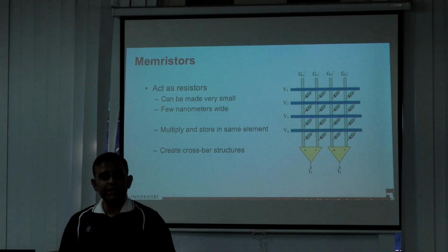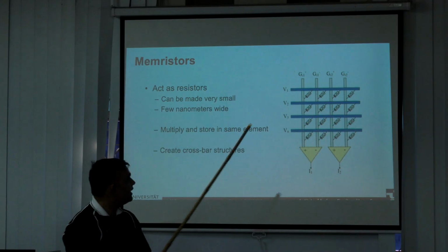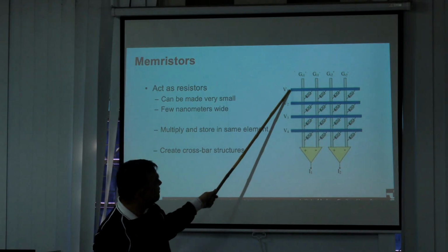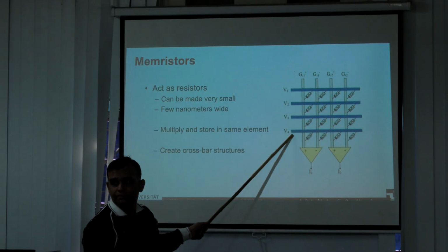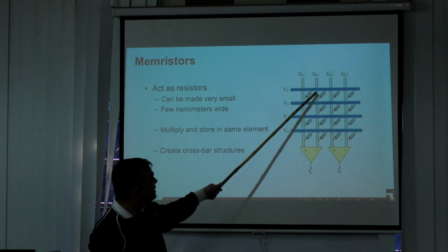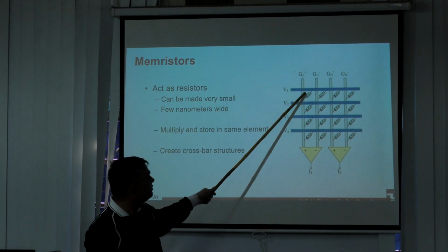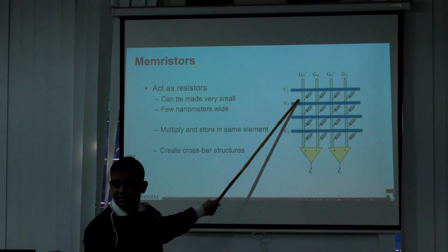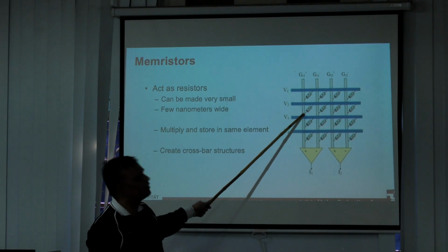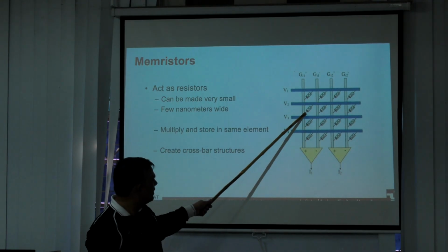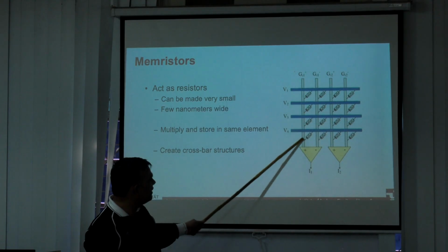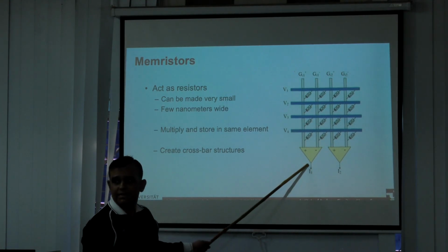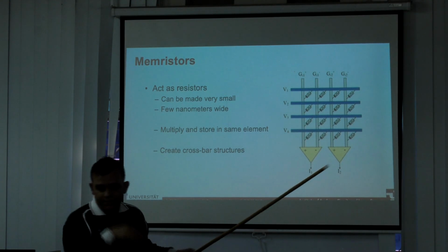which means we can make something like these crossbar arrays, wherein that's my input signal V1 and so on. These can be multiplied with this memristor, plus it's the same current, so current in series gets added. This can be multiplied, current in parallel gets multiplied with this resistor, and then we can feed this to a summing amplifier at the end.